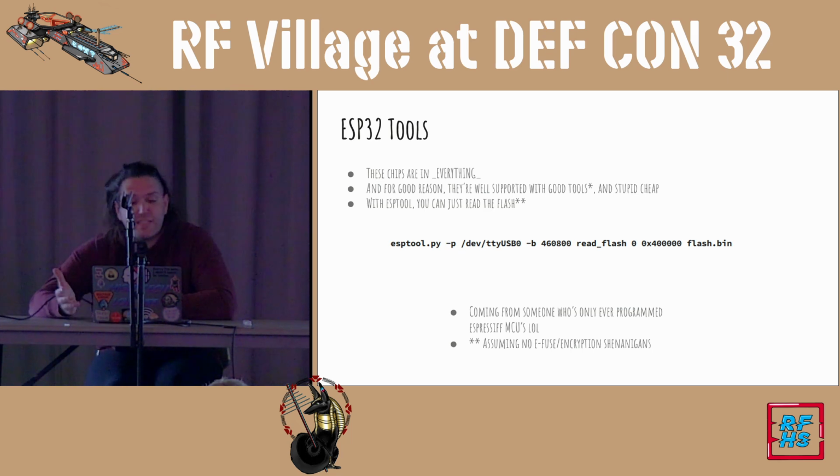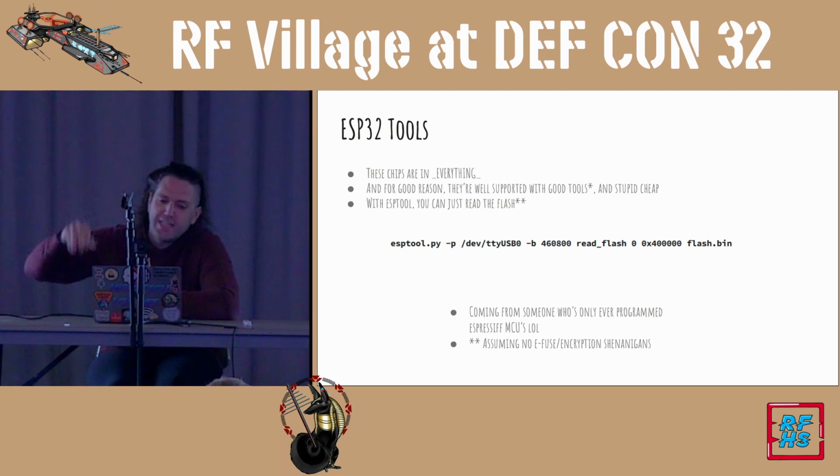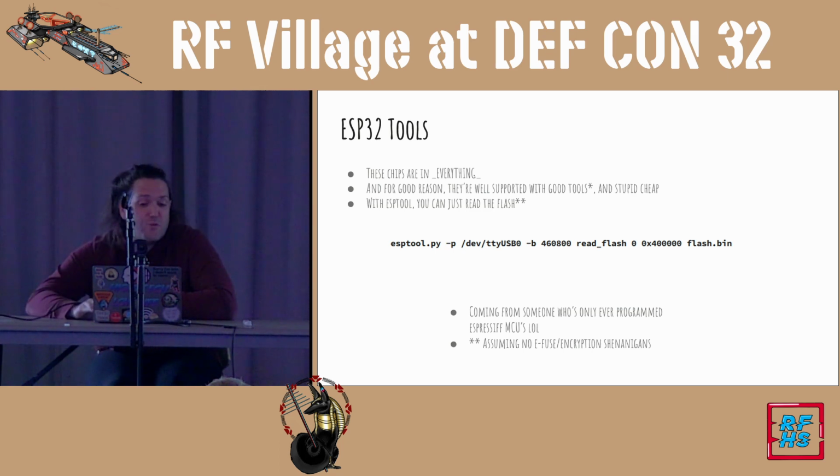And at least in my opinion, granted I've never actually programmed anything other than an ESP32, sorry, STM32 fans, the tooling is good or at least adequate. And with esptool, you can actually just read the flash. So assuming we're able to figure out how that serial UART's broken out, figure out the baud rate, all of that good stuff, you can just get the firmware, assuming no eFuses have been burned in, which is generally not the case, and we'll touch on that a bit in the conclusion.